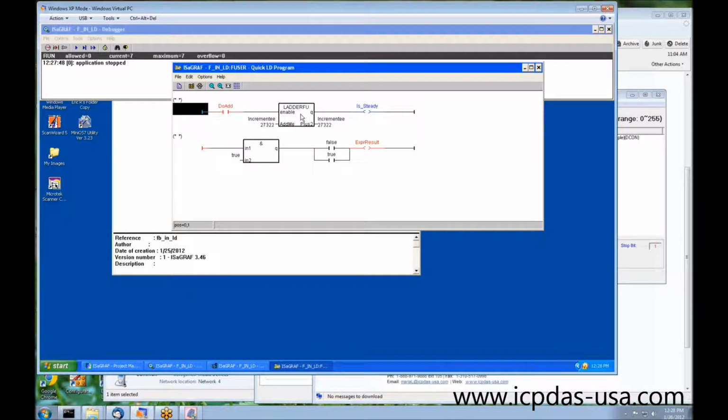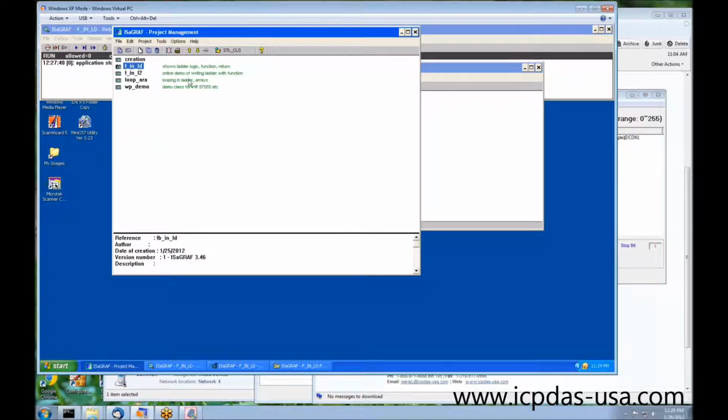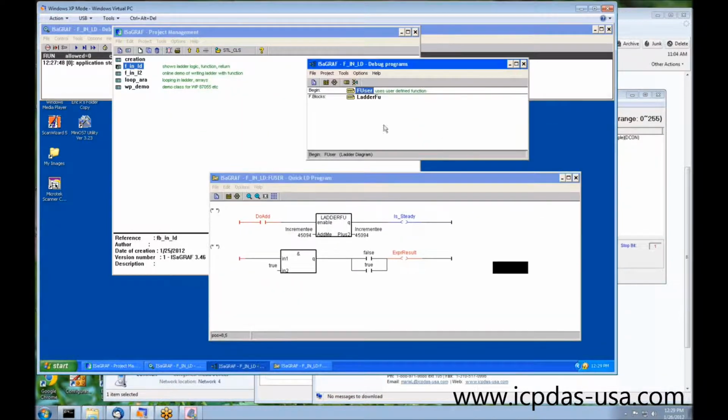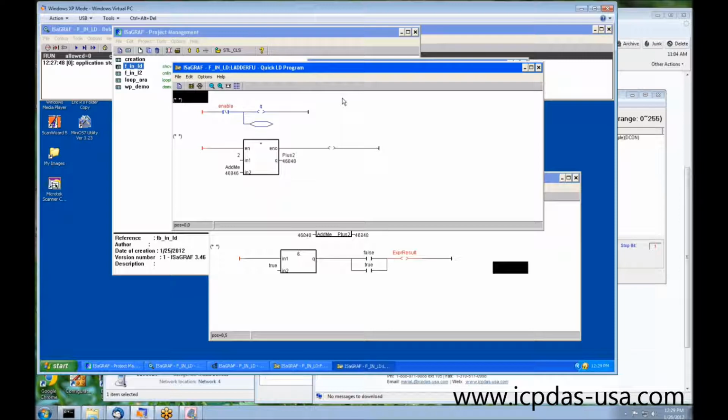That means that it's doing this rung and that rung every 2 to 7 milliseconds. And when it hits this rung, it is also doing this other function that we defined as well. So it's really doing 4 rungs in that speed.